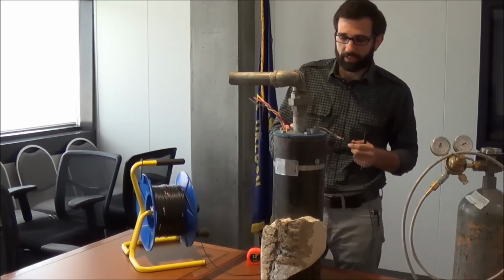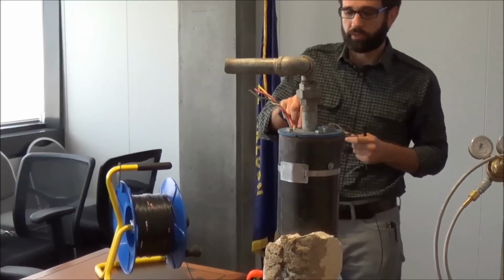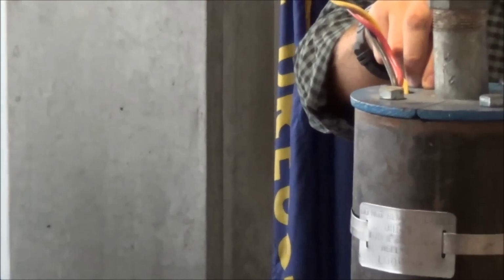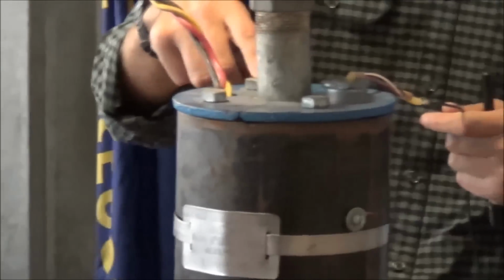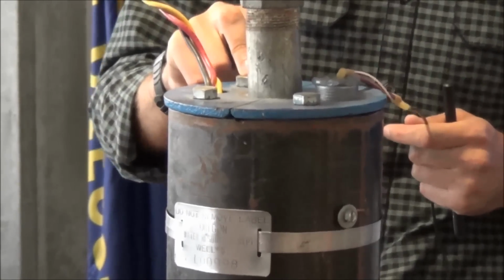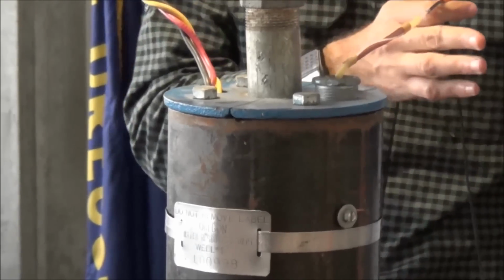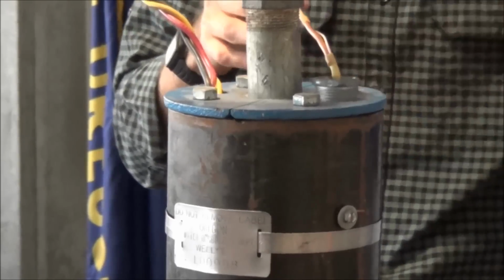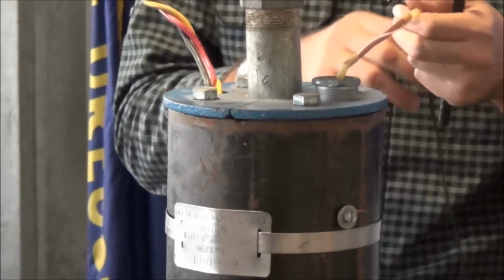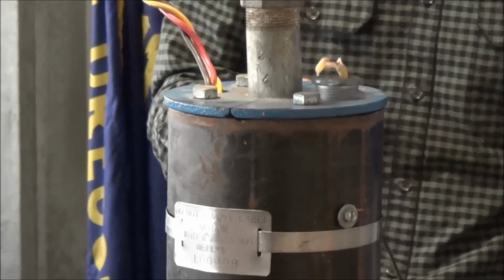And then finally, try another way in. If we look at this as an example, this is our main access port. But on the split seal, we can actually remove a bolt and try to go in another way. You can remove typically one of these bolts and not have any problems. So we'll try to go in that way. Maybe the liner is set off to the other side or something, so we're getting stuck, can't go down this way, or just not having any luck. Always try another way, and usually you can have success.